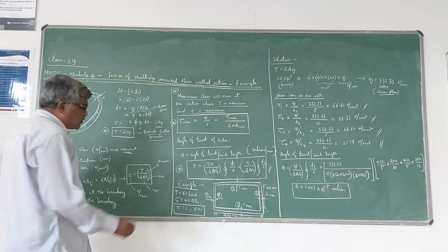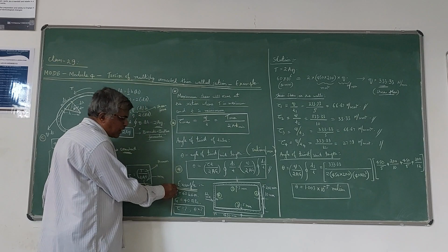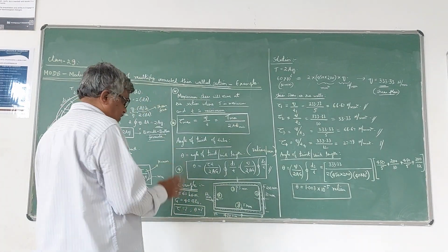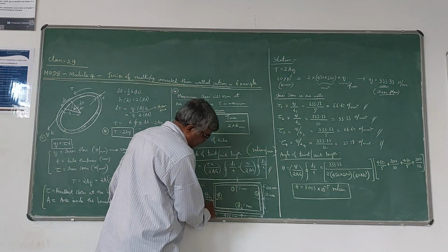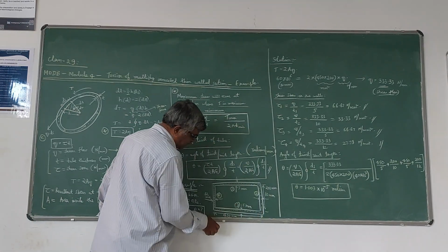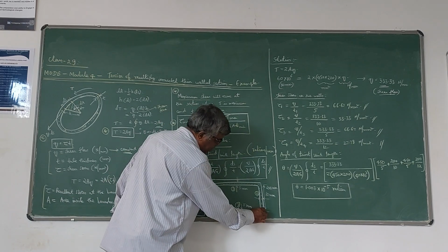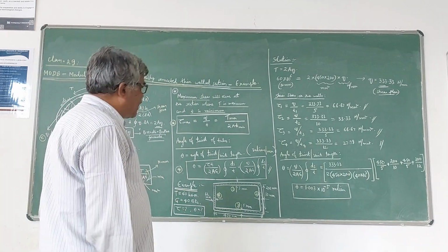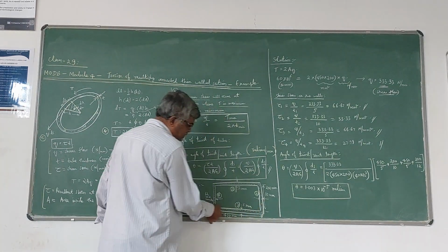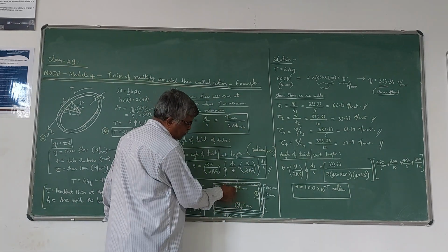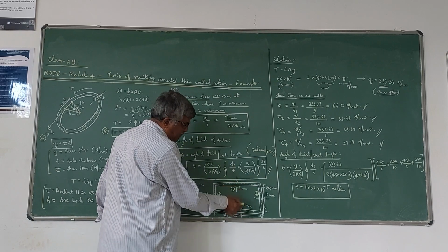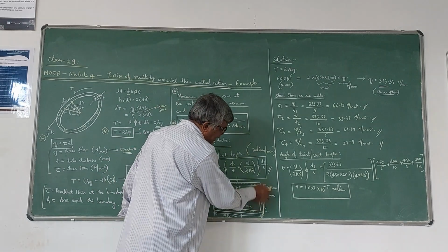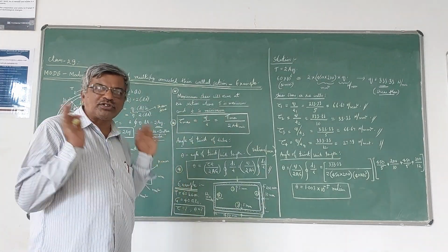Now this can be understood by taking a simple example of a rectangular tube. So this is a rectangular tube with different thickness. So the length of the tube is 450, center to center length. You can see here, this is center to center length. The dotted line shows the center line of the tube. 200 mm is the width, 450 mm is the length. Thickness varies. So top it is 5 mm, bottom it is 5 mm, left side is 12 mm, and here it is 10 mm. So now we have 4 segments here.